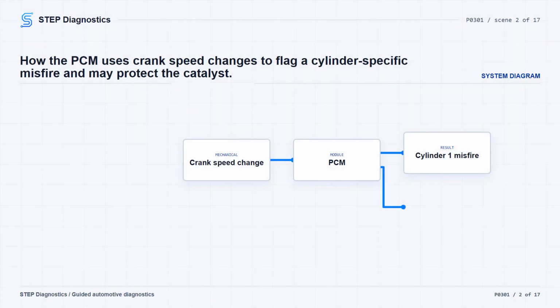Broadly, this kind of fault can come from ignition, fuel delivery, air leaks, connector problems, valvetrain or compression issues, oiling or VCT concerns, carbon buildup, or a control side problem. Start with the basic system checks and follow a structured diagnostic approach. Do not assume the coil or plug is bad just because the code names cylinder 1.